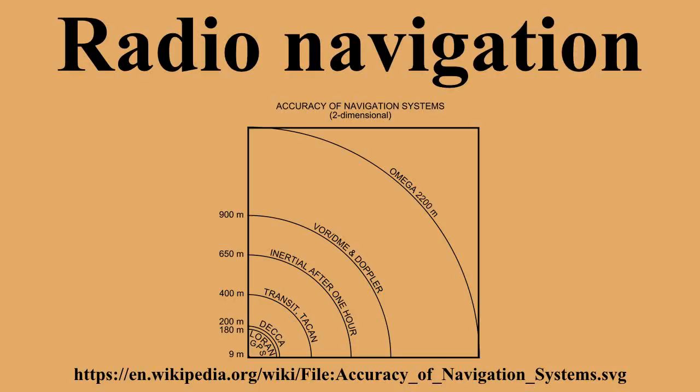Hyperbolic navigation systems are a modified form of transponder systems which eliminate the need for an airborne transponder. The name refers to the fact that they do not produce a single distance or angle, but instead indicate a location along any number of hyperbolic lines in space. Two such measurements produces a fix, as these systems are almost always used with a specific navigational chart with the hyperbolic lines plotted on it, that generally reveal the receiver's location directly, eliminating the need for manual triangulation.